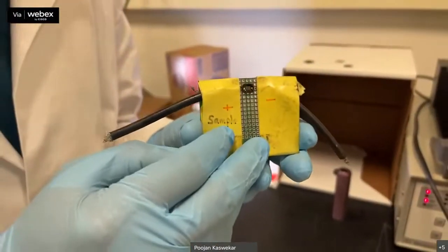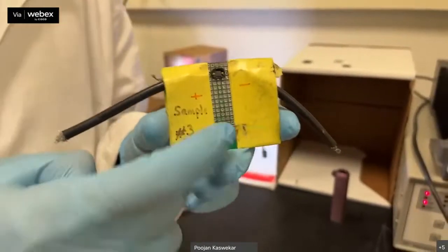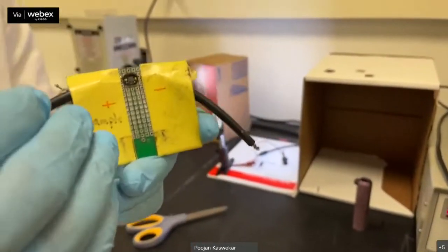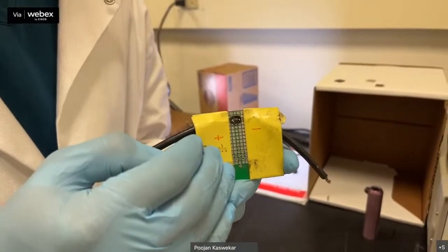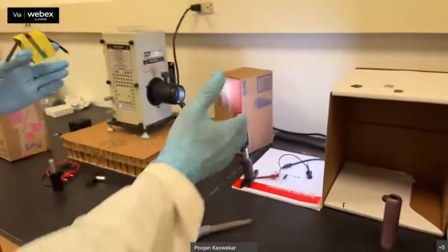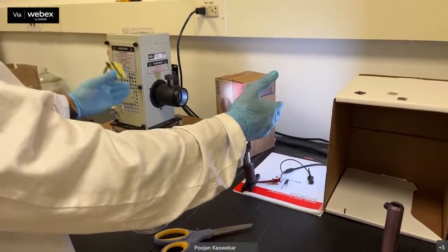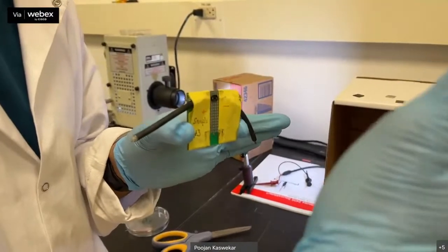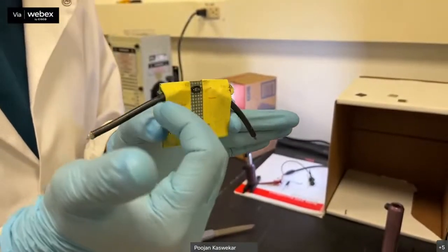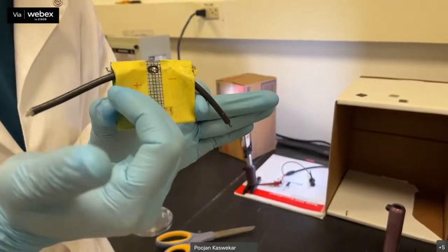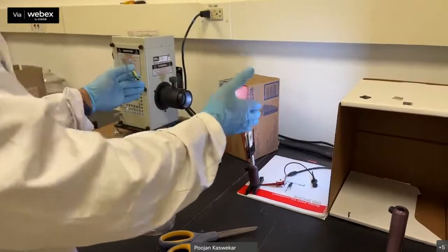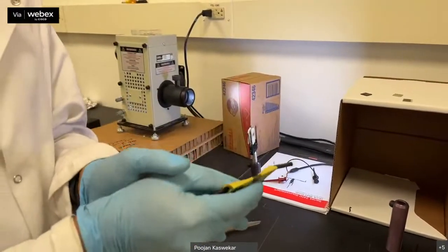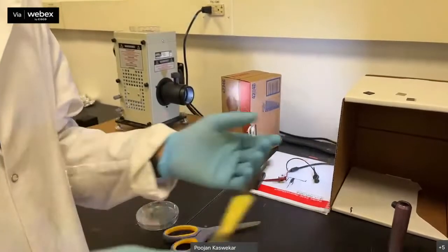The sample you are seeing here is called the reference sample, and this is from NREL, National Renewable Energy Laboratory. They calibrate solar cells for us and send them to us. Typically this solar cell gives you 1.64 milliamperes of current. In order to set the distance between your sample and the solar simulator, you need to know at which place you are getting 1.64 milliamperes per centimeter square of current. So first you need to measure the IV for this sample, and you will set up 1.64 milliamps. There you will know this is giving one sun illumination. Then we will remove this and place our sample at the exact place to get that one sun illumination and measure the IV characteristics.